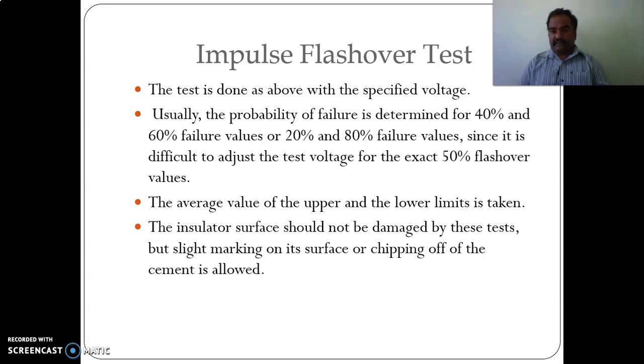And during these tests, the insulator surface should not be damaged. Only flashovers must be experienced. So, you must see only flashovers, but not any punctures or damage of the insulators. At least most of the surface will be intact. So, small chipping will be okay. Small marking on the surfaces will be okay. They can be subsided. So, major damages must not be there. No punctures must be there inside. No internal discharges. Your damage must be limited to small chippings.